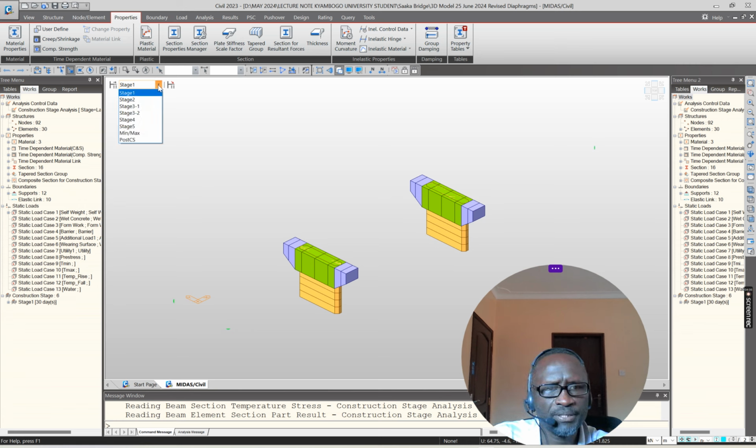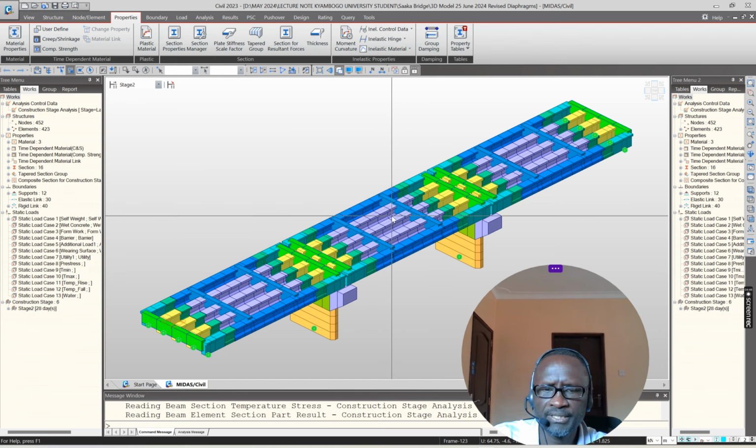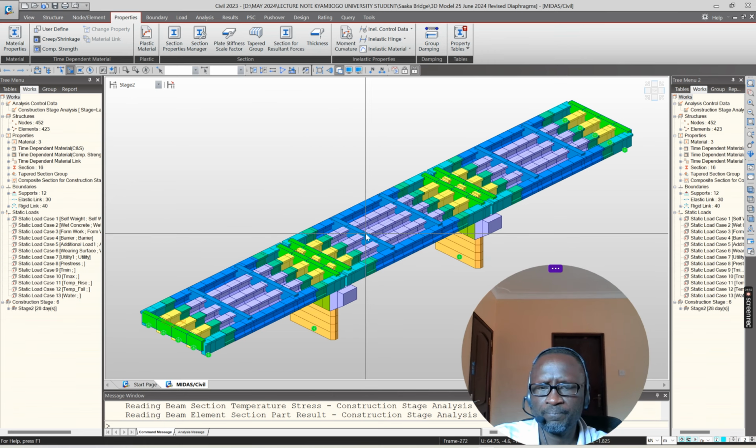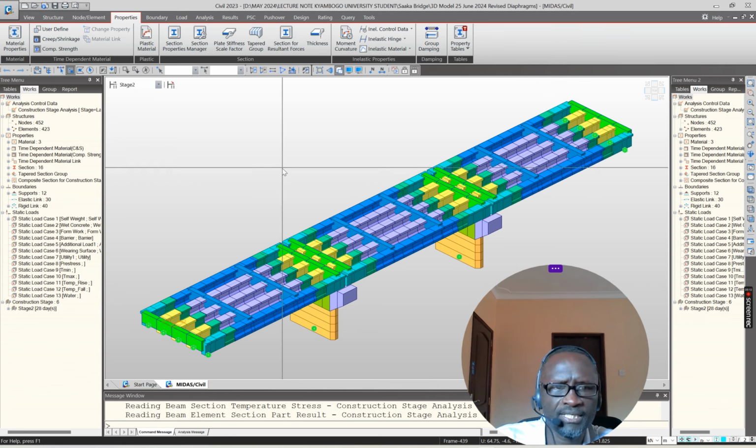Once that's done, you prepare the deck system and prefabricate the girders. After that, you bring them up using a crane. The contractor used a crane to lift all these, and you design for lifting as well, with a proper anchoring system, to avoid any bang and any deformation while in transit to the location. Extra bars may be required, so you have to design for that also.